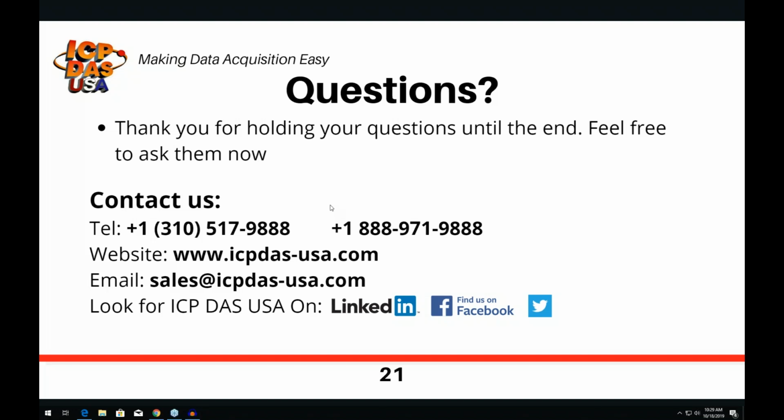I would just like to point out that question asker Paul Chidley has pointed out that I was wrong in answering about registers and coils. Coils are 1-bit registers, and the registers are 16-bit. Coils are used for digital output statuses, typically on or off, or actually always on or off. So it'd be 1 represented by on, 0 represented as off.